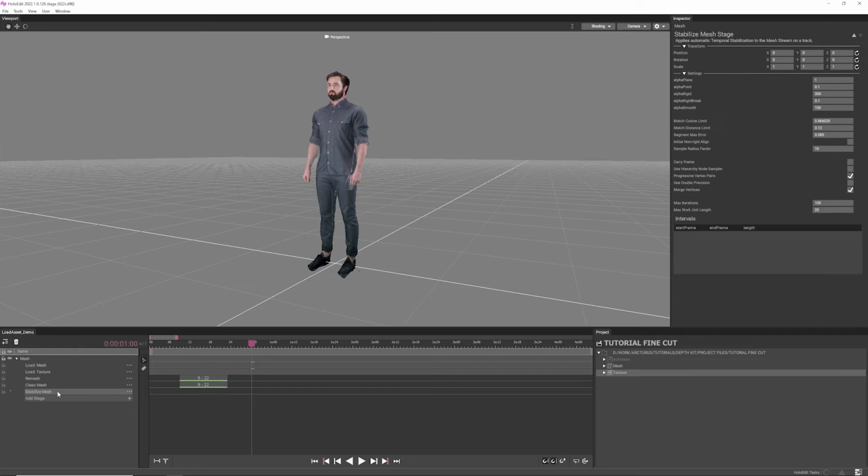If you're finding consistently bad results from the stabilized mesh stage, you can decrease this value. But keep in mind that smaller segments reduce compression. Start with the default value. Then, if you find you are seeing long segments with bad deformation, try decreasing it. Start with 0.05 and decrease further as necessary.